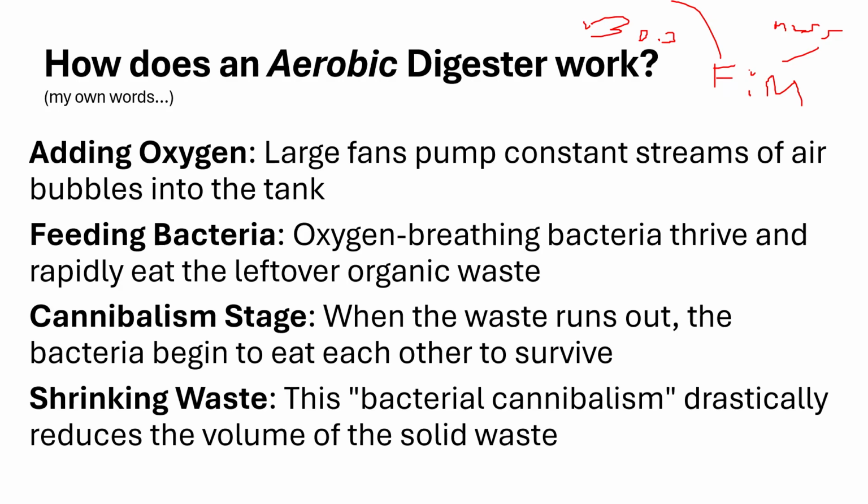I have a stylus with me, so let me rewrite it here. Here we go. That's a little easier. Food to microbe, that's going to be represented later on by our MLSS, mixed liquor suspended solids. And we're going to calculate our BOD. And we're going to find that based on what our food to microbe ratio is, we can take a look at the age of the sludge. We can take a look at what we need to adjust in our process to keep our good bacteria going and get rid of our bad bacteria or microbes. So we'll go over this, but I'm kind of foreshadowing what we're going to see in activated sludge processes, okay?